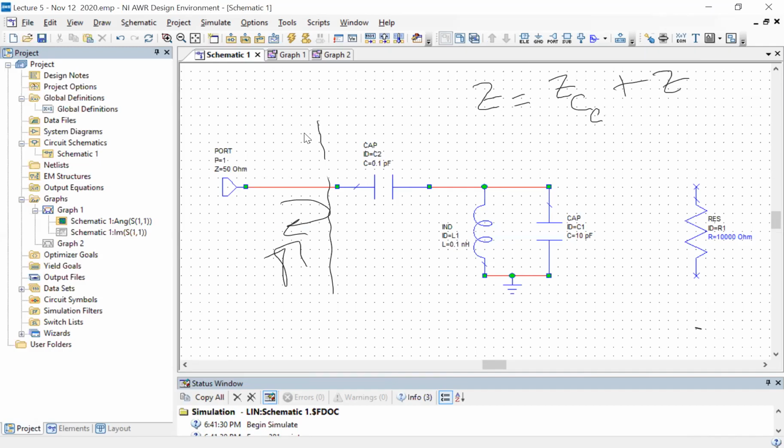Again, I realize there are too many confusing symbols because I wrote Z_R for the characteristic impedance, but now let me put it as Z_LC, the impedance of this guy. So it's this Z which will go in the formula for the reflection coefficient. Maybe I'll just call the reflection coefficient gamma_R as (Z minus Z_0) over (Z plus Z_0).